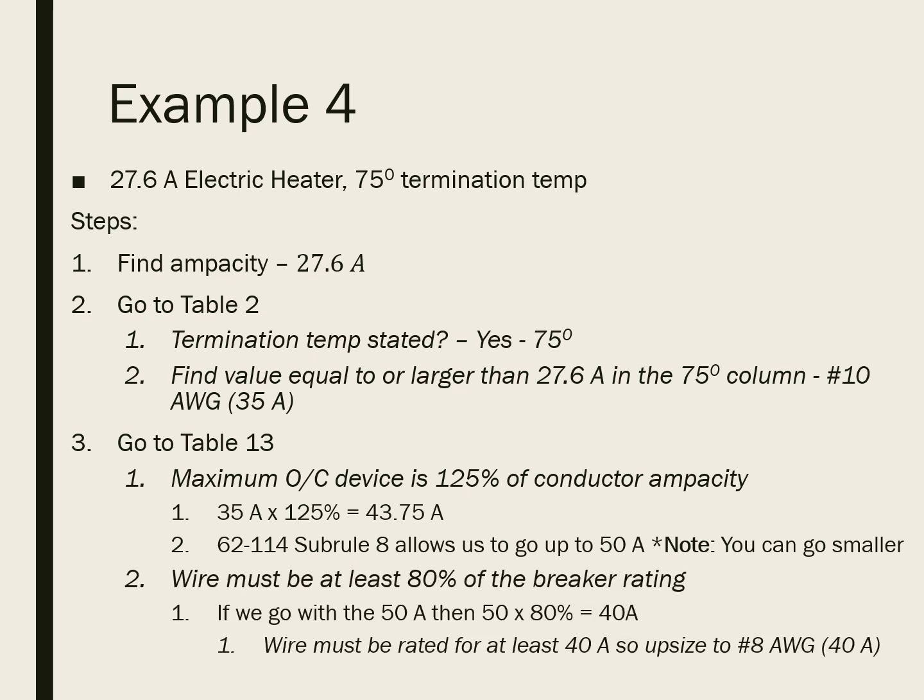Since my wire must be at least 80% of my breaker rating, if we go with a 50 amp rated breaker, then I must go with at least a 40 amp rated wire, which bumps me up to a number 8 conductor.